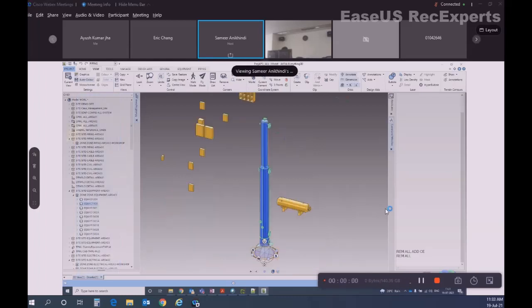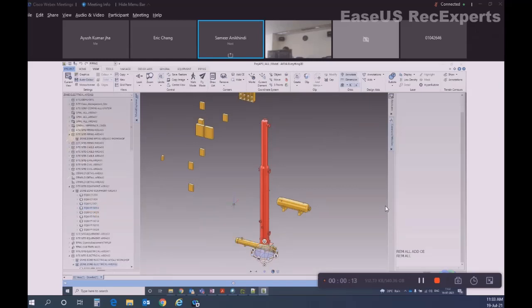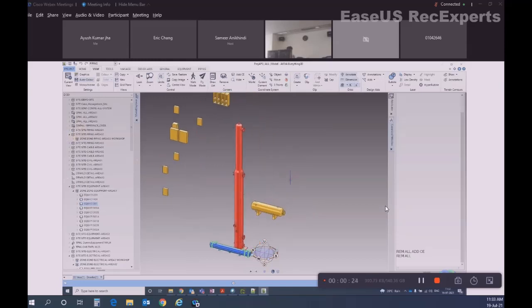Z enter. Hundreds and hundreds of elements added, and you are not able to see clearly with your eyes. So you can right click, 3D view select, and then Z enter. See, as soon as you start typing, it will unselect it. So that's why I told you to use middle click to press. Don't use right click. Z enter, O enter.